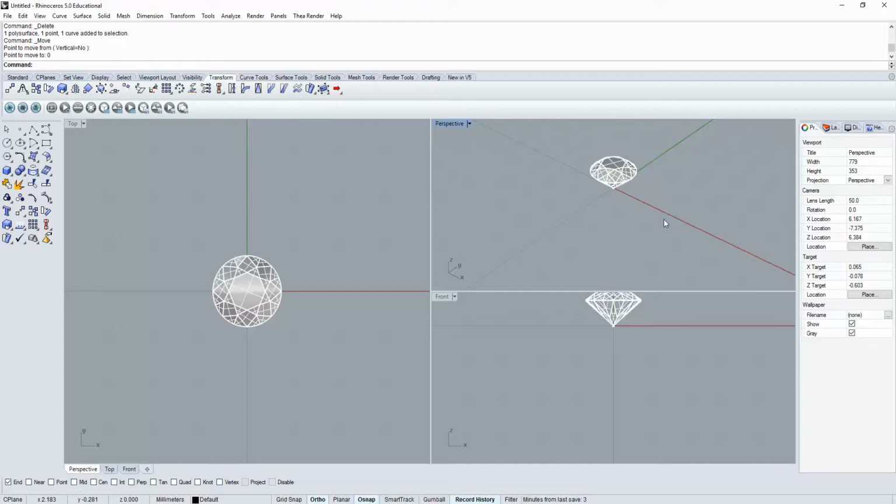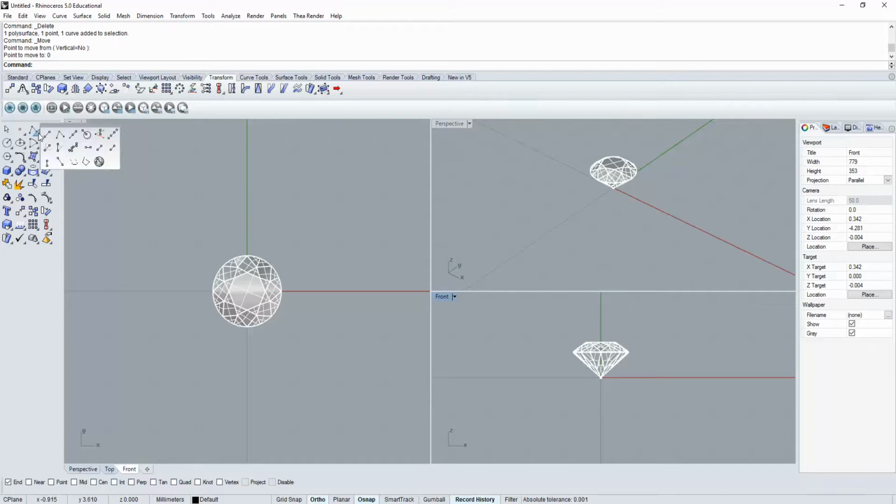The first thing I'm going to do is, because I haven't given you a cutter with the gem, you're going to have to make cutters. It's really easy. All you want to do is draw another line, snapped to your girdle, straight up. In this case, I'm going to call this the crown wall of my cutter, and I'm going to make it 1 to 1.2 millimeters tall.